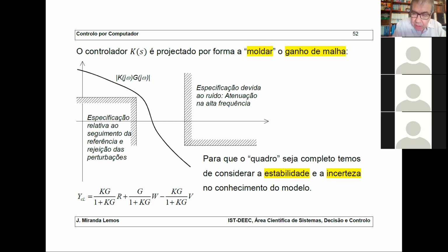So in the case of the integrator, as you said, the transfer function is 1 over S, that's 1 divided by j omega, so the gain is 1 divided by omega. So the loop gain is decreasing, as it should be, okay? So if you force an integrator, you are going to have something that decreases in frequency, very high at low frequencies and very small at high frequencies, okay?